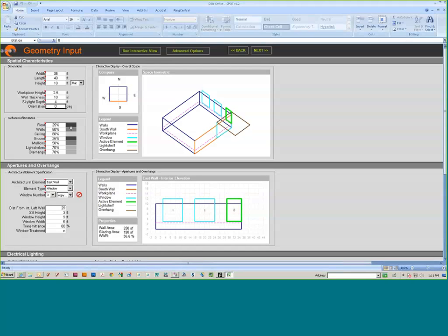I did leave the reflectances pretty much standard. I didn't go into great detail on those. What guidance do you have for trying to figure out the reflectance of carpet or a paint swatch? I think it's mainly the walls and ceilings. Okay. So typically, if we have one of those off-white colors that we have on the walls, it's typically 70%. But again, that depends on how many sketches and things are hanging on the wall. That'll alter that reflectiveness. So 50% is a good average, and take a look at what you have in that space. And if it's pretty much blank walls, just white paint, then I would suggest going to 70%. Okay. And ceilings, typically the grids that we have, they range about 80%, so that's pretty normal.